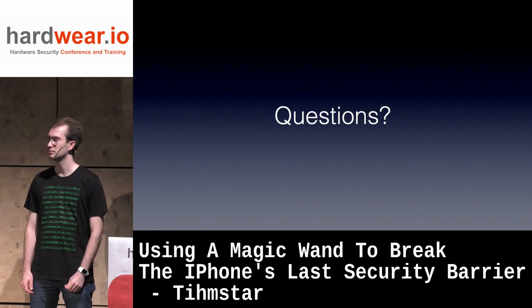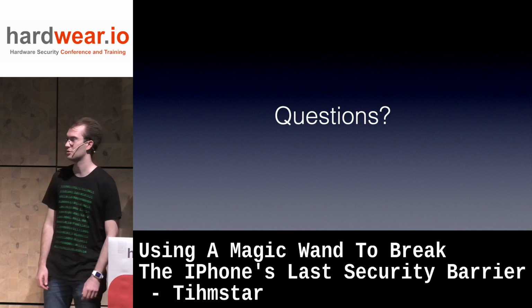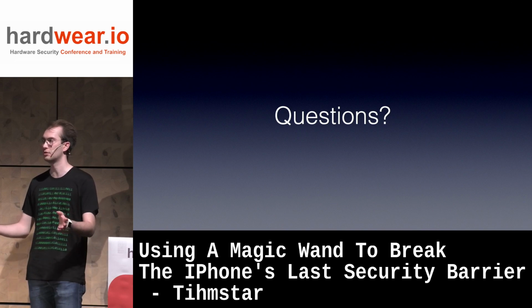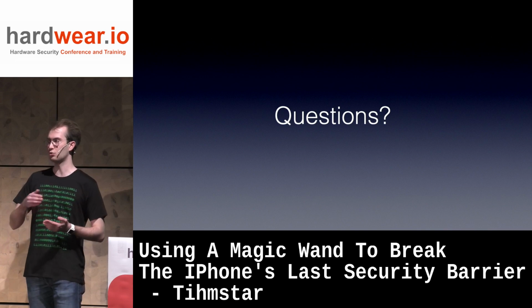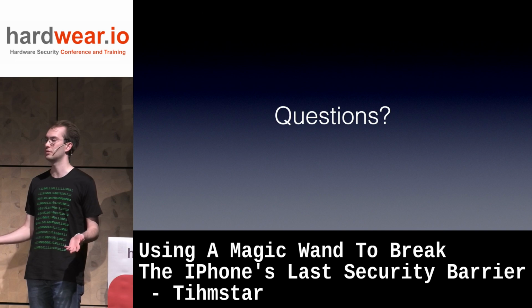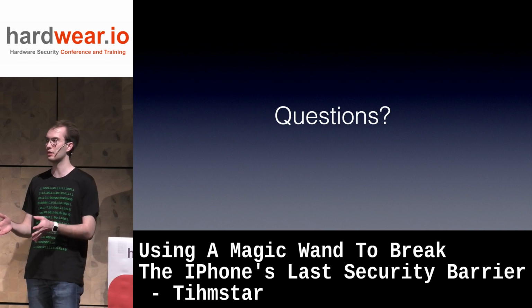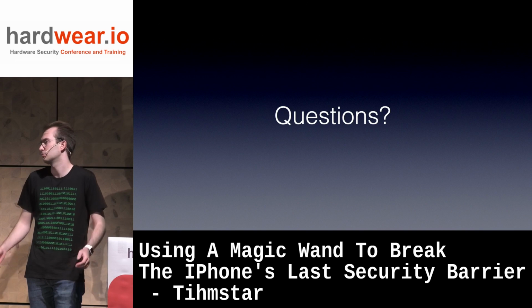Thanks. And another question: I'm not familiar with the actual AES implementation on this chip. Is that not protected? It's a black box. Nobody knows. It's not something that's documented. None of this is documented. You can reverse engineer the bootloader to figure out how to talk to the hardware, but no idea how it's actually implemented. So from the side channel, I built a model, which I think is how it works, but no idea if it actually works like that.